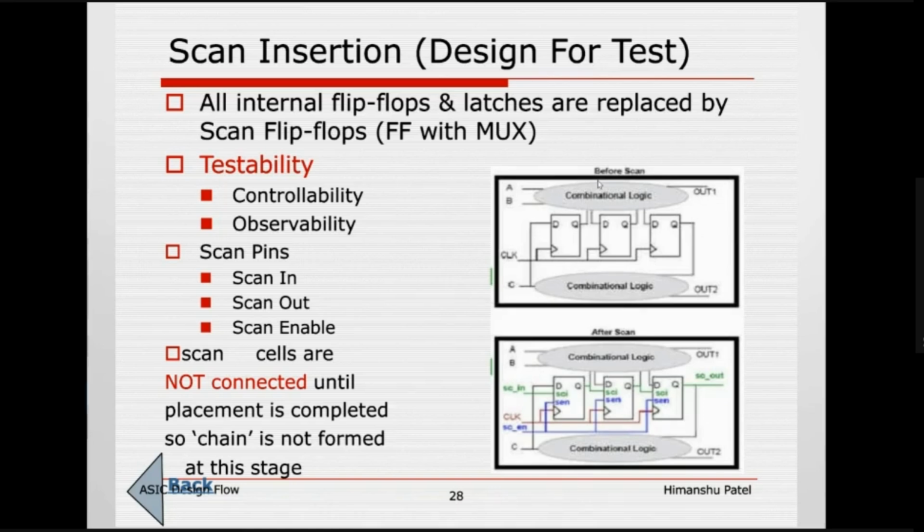Fault free means, as I explained in previous slides, we have stuck-at faults. For example, the D input is not grounded, the clock input is not grounded, or the clock input is not directly tied to the power source. Illegal connections or anything. This can be verified by functional verification also.